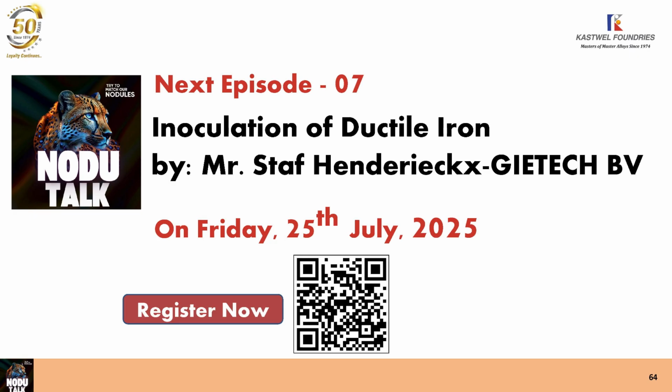Therefore, the best combination is a pressurized, non-pressurized pouring system. Then you have the lowest contact with oxygen. In the casting itself, the metal speed should be less than 0.75 meters per second, and if possible half a meter per second. If that's okay, inside the mold you will not form extra dross anymore.